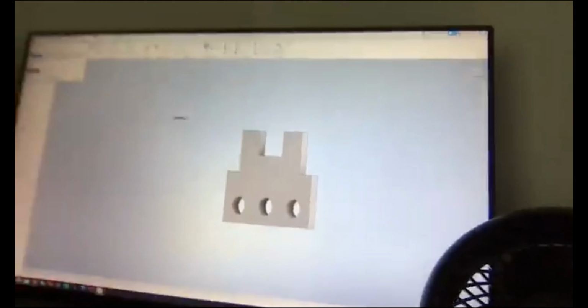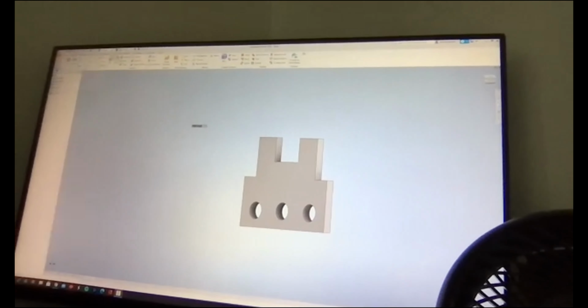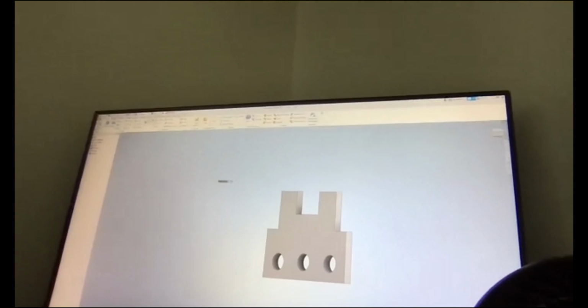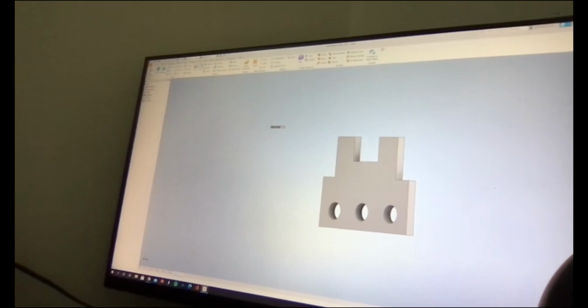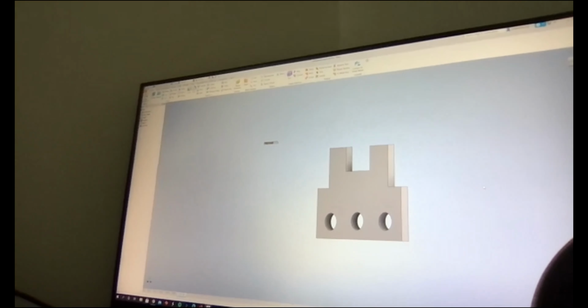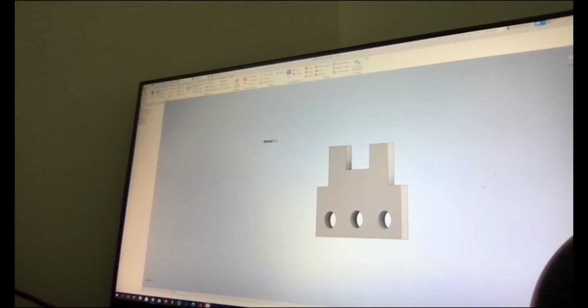I just extruded it. I did not have the option to set the thickness. No need to worry about the dimensions because we don't want dimensions in an isometric pictorial, right? No, not that. I'm talking about the thickness. Remember, I asked you about the thickness. We have to type the thickness, like 15 mm, 12 mm, 10 mm.